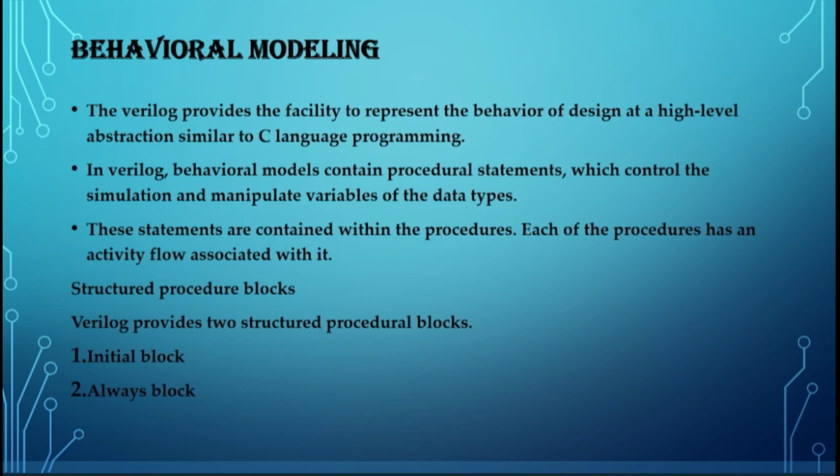Because of that, when you are designing such complex circuits, you don't think of writing the code at gate level or data flow. There should be some high level of abstraction used by you in order to write those types of protocols, and that is behavioral level modeling. That is why behavioral modeling is called the highest layer of abstraction, because you write your code based on a certain algorithm, based on the behavior of your circuit.